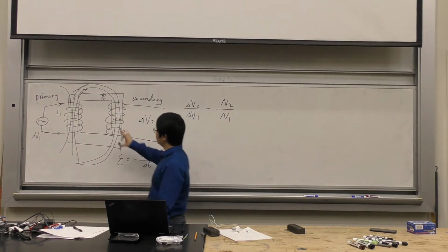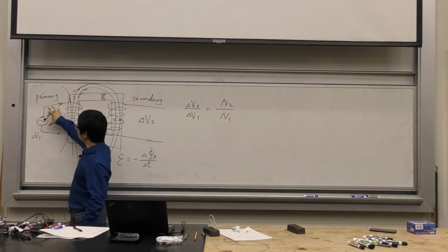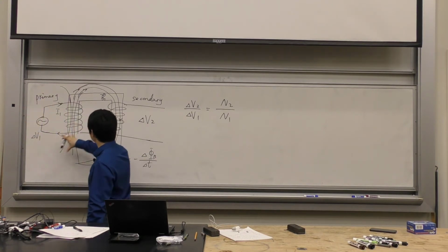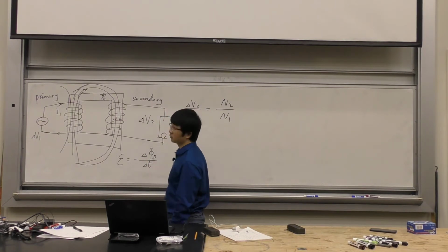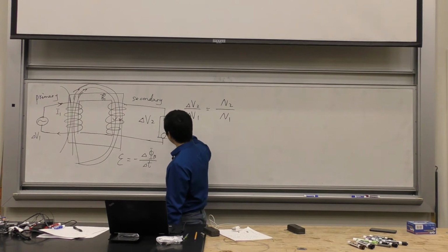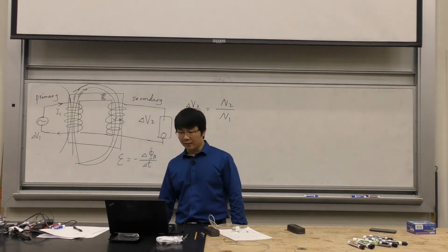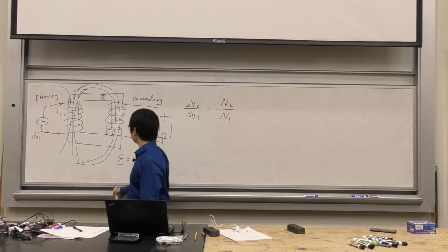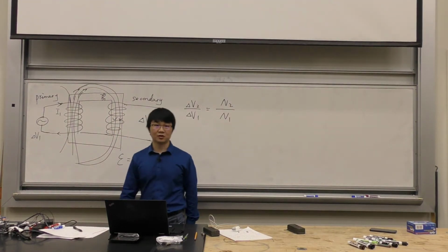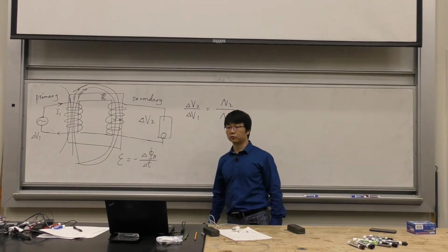So in this case, say this is the charger, okay? This is the transformer inside the charger, okay? You connect it to the wall outlet. This is the wall outlet. You want to get a voltage, so you're going to connect to your iPhone here, okay? The voltage you want to get on this side is going to be 5 volts, right? You want 5 volts to go to your iPhone, okay? And then we know that the primary winding has 92 turns. Which one is primary? This is primary, right? So we want to predict how many turns are on this side, okay? So now you know which one is which, so you can plug numbers in. We're trying to find N2, not N1, okay?